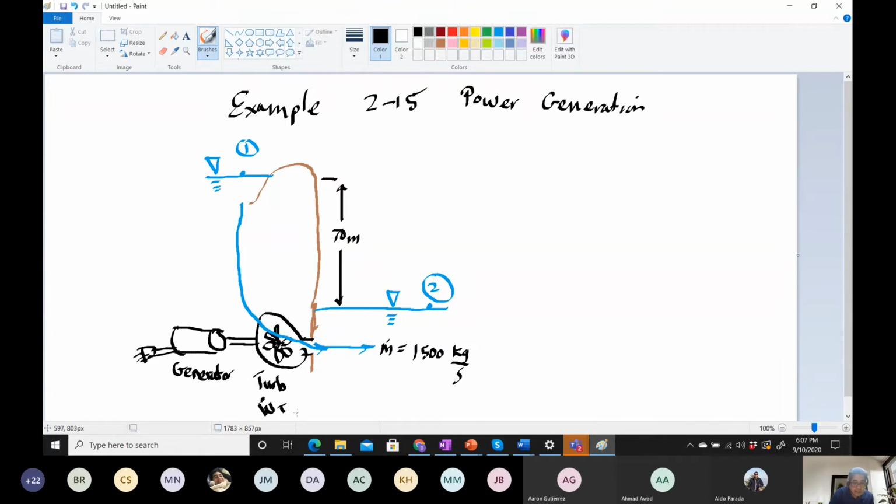the dot, is equal to 800 kilowatts. In other words, that's how much we're getting out of this turbine. And then it says the electric generation is 750. So what's happening is we're getting electricity coming out here. So I'm going to say electric generation is equal to 750 kilowatts. So that's what we're recouping, basically.